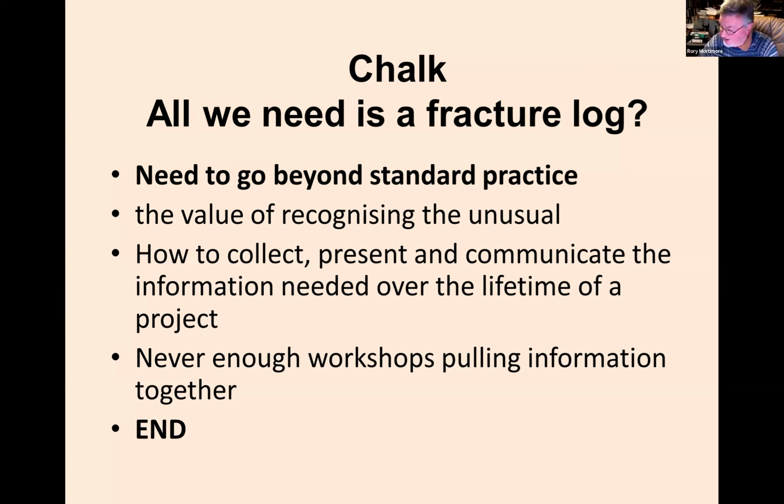I've been in court sufficiently often having to hand my notebooks in and things like that and cross-examined by QCs who say, what's the evidence for these fractures being open? Or what's the evidence for the strength that you've applied to the chalk here and so on? And if you haven't described your method in your log, and you haven't said, well, if I'm testing the strength, this is how I've done it, then you can be very open to a lot of criticism. So both in terms of the strength or the density of the chalk and in terms of describing the fracturing, it's very important that the description is there to go alongside the classification.